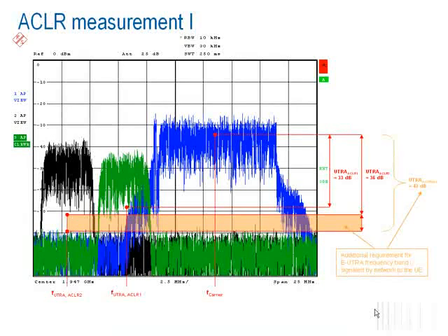Also in the uplink we need to measure the ACLR. As you can see here, we have the same requirements as in the downlink for LTE FDD. First, we assume the presence of an LTE signal with the same bandwidth, and as shown here in the graph, the second part of the ACLR measurement is the presence of a 2G or 3G signal. Different limits might apply here as shown. For example, for UTRA frequency band 1, the second limit would be reduced to 43 dB, which is a very challenging limit, and so the performance of the transmitter needs to be verified against these tolerances.